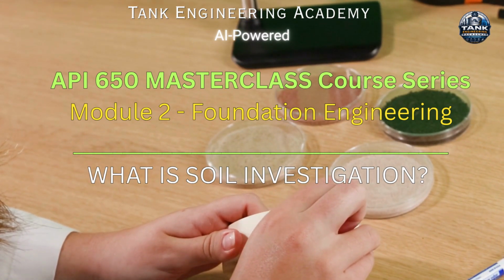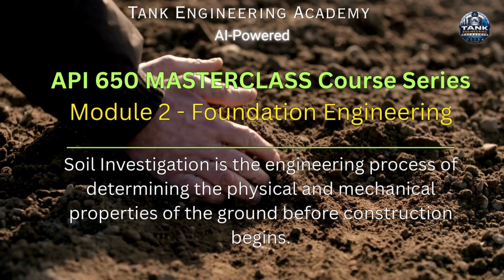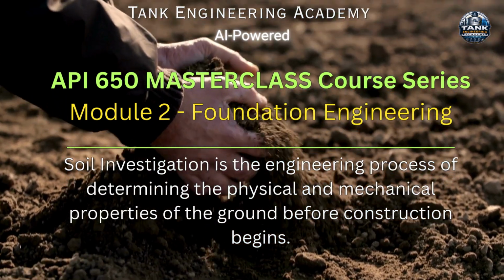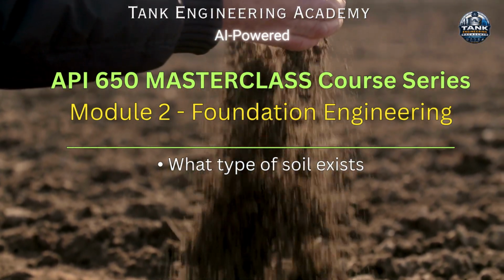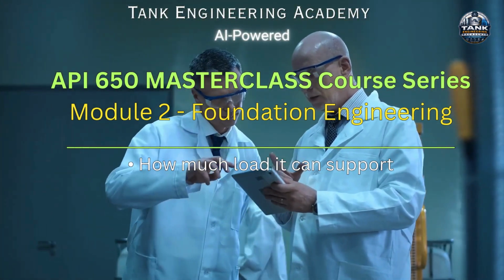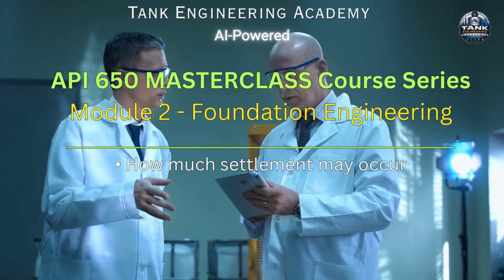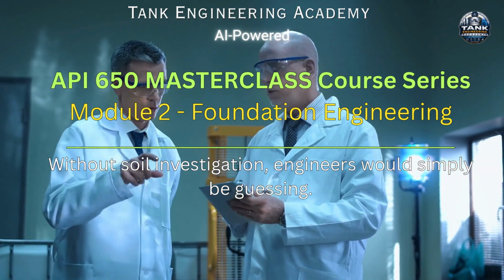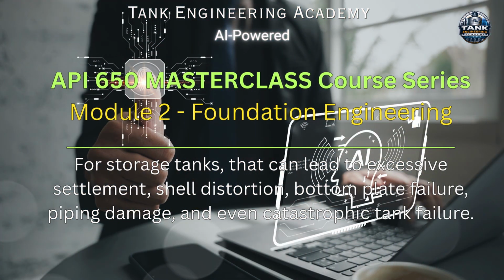What is soil investigation? Soil investigation is the engineering process of determining the physical and mechanical properties of the ground before construction begins. It tells engineers what type of soil exists, how strong the soil is, how much load it can support, whether groundwater exists, and how much settlement may occur. Without soil investigation, engineers would simply be guessing. For storage tanks, that can lead to excessive settlement, shell distortion, bottom plate failure, piping damage, and even catastrophic tank failure.